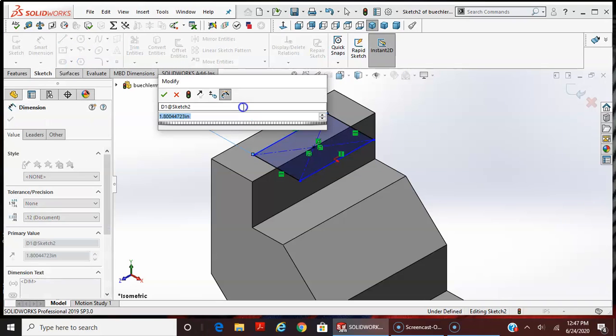Then Smart Dimension, this line length. On the drawing, you need to do a little bit of interpretation, but the value between the two through holes is 1.5 inches, and on the right side view of the drawing, near the isometric or the pictorial view, it shows a value of 1.25 times 2. So that applies to the slot. So the 1.5 value only applies to one feature, and that's the distance between the two holes.